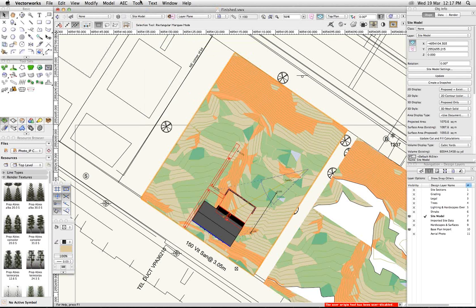And in fact, in dealing with anything geo-referenced or just a long way from origin, the biggest takeaway from today is, no, you do want to go through this process of centering all of your information over top of that internal origin, but then adjusting it so that the rulers are correct, meaning when you export later on back to DWG, the people at the other end will receive it in exactly the same XY position that they sent you the original file.